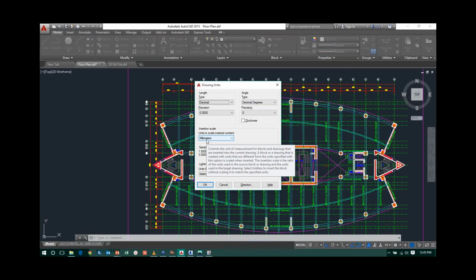And if you are trying to import multiple floor levels from AutoCAD DXF, where each floor plan is different, then there should be one common point aligned for all the floors. If not, they will be taken at different positions. So the first thing to consider is unit system consistency. The second is that the base point for all the AutoCAD drawings should be the same for all the floors.